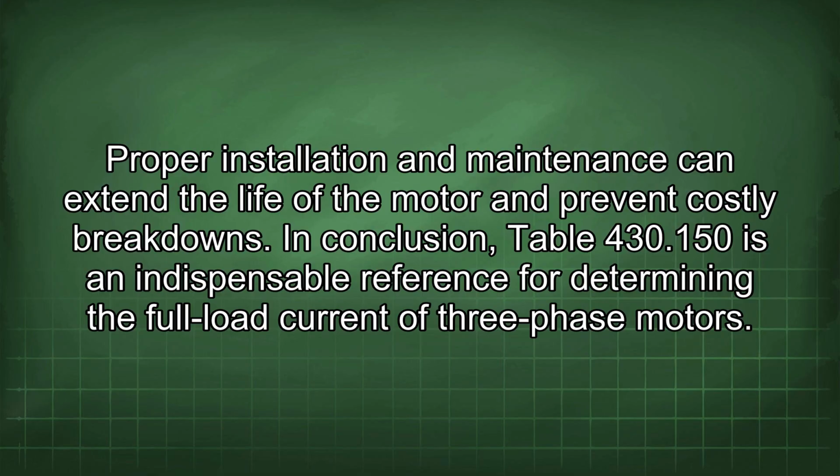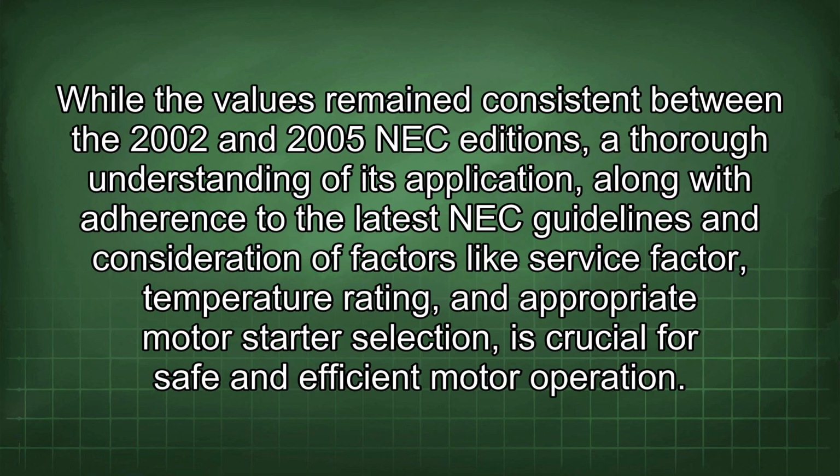In conclusion, Table 430.150 is an indispensable reference for determining the full load current of three-phase motors. While the values remained consistent between the 2002 and 2005 NEC editions, a thorough understanding of its application, along with adherence to the latest NEC guidelines and consideration of factors like service factor, temperature rating, and appropriate motor starter selection, is crucial for safe and efficient motor operation.